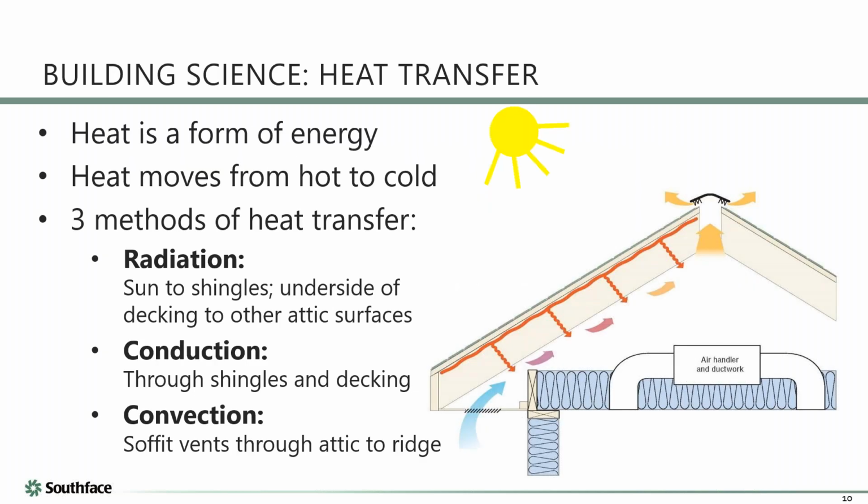Joey, you want to talk about heat transfer while I try to untangle myself? Sure. We've been building on this, and this is the culmination of it. When we do load calculations, what we're really trying to find out is how much heat is entering or leaving the home. So it's important to understand the basics of heat transfer, and that it comes in three forms: radiation, conduction, and convection. We'll talk about each of these as we go along.